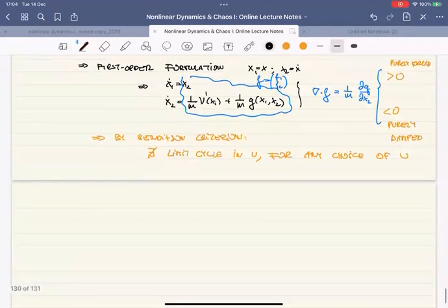Let's be a bit more specific. If I now consider a completely general mechanical system, say badly nonlinear, with a very complicated potential, and what I'm adding to it is what we customarily write, which is kx dot, linear damping. Then what is my g of x, x dot?